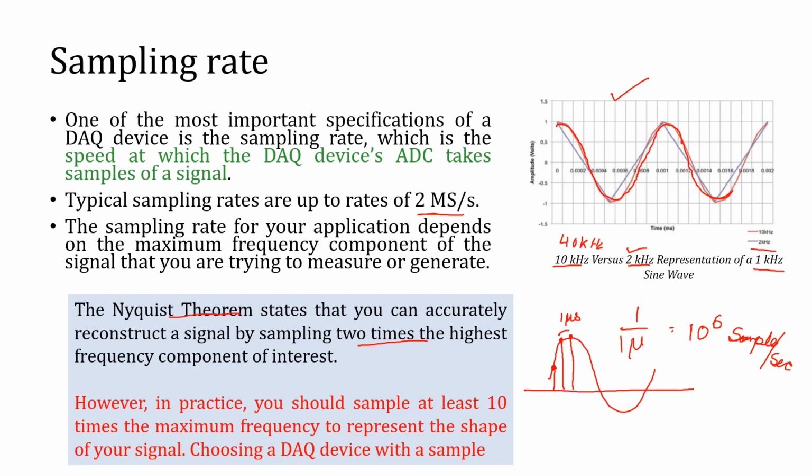So the sampling rate is very important. It may totally change how the signal looks when we are acquiring it in terms of digitizing. That is, after A to D, it will drastically change the behavior of the system. So sampling rate is very important once we are interfacing the signal.